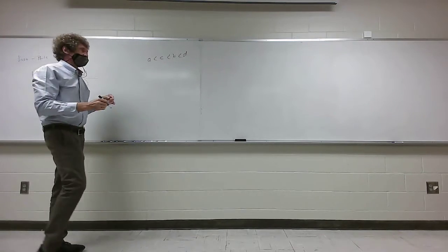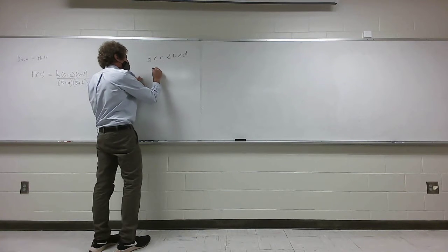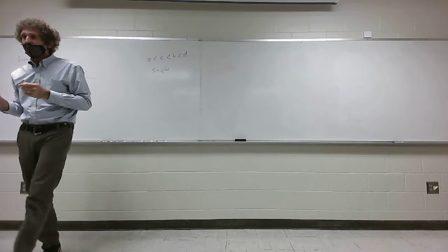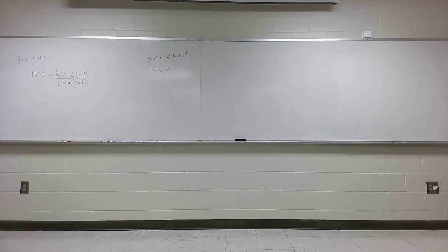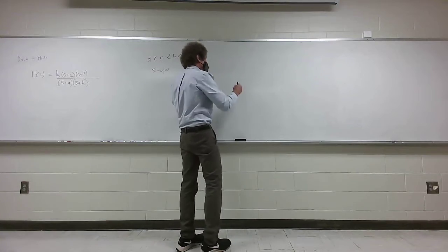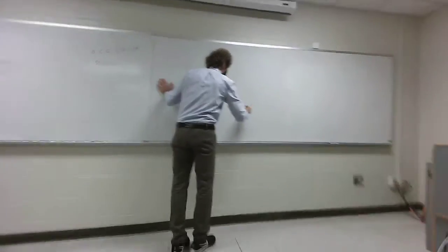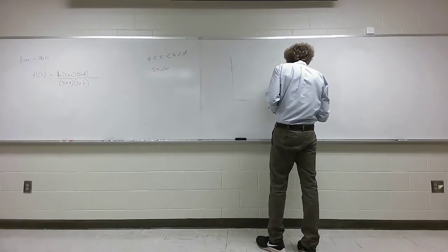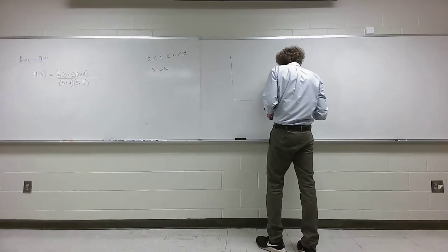Then I'm going to say that S is really complex, but we're just going to have S equal J omega. This is common. We ignore sigma. So this is really something where the S is just the complex portion of the complex frequency. It's just the J omega term. And then what we usually do when we talk about Bode plots, here we plot the log of either omega or S, log magnitude.